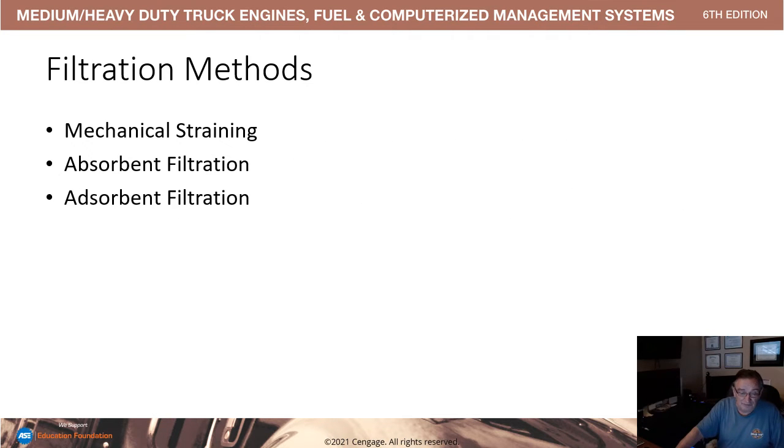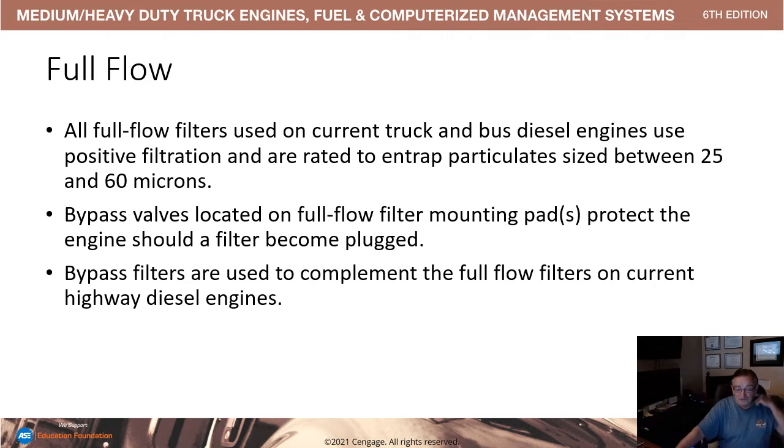Filtration methods: mechanical straining and absorbent filtration. Full flow filters used on current truck and bus diesel engines are rated to have a particulate size between 25 and 60 microns.